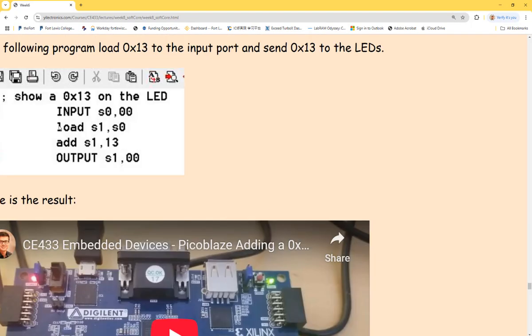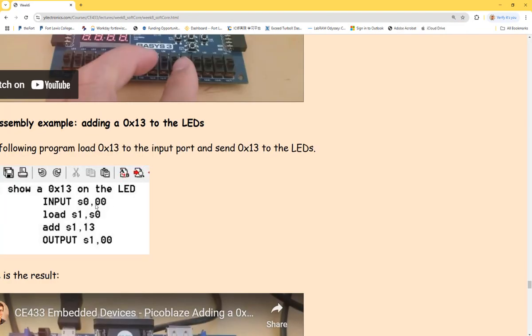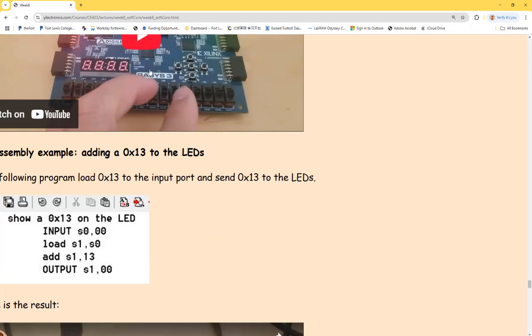There are so many different ports, and you can use any one you want. I used 00. There are 256, so it's from 00 up to FF. The only thing you want to specify is that this one needs to be shorted to the switch. You'll see the example code provided in the tutorial. Basically, I connect SW to input, so eventually the switch is being shorted to all the input ports. We're not using any other ports, so it's fine.